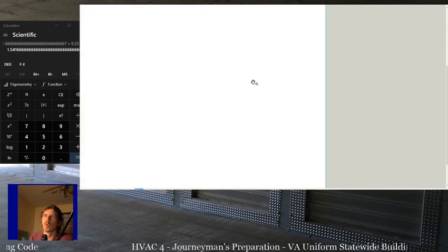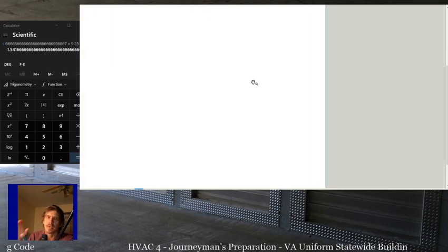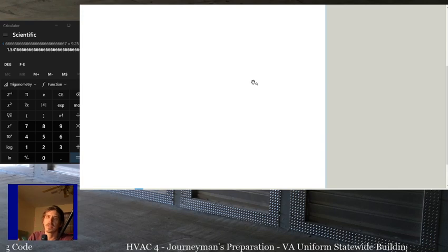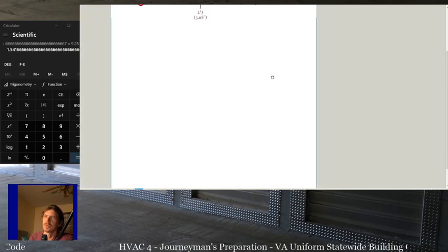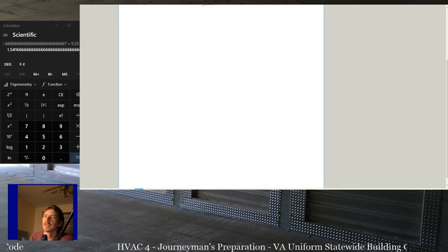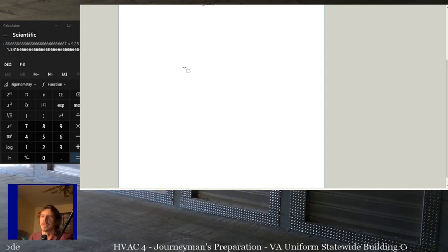Any short wall is usually a non-bearing wall. Generally, bearing walls will end up running almost the entire length of the structure. And if you get used to residential construction and even commercial construction for that matter, you can usually figure out what's bearing and what's not. But it's not something we can cover in this class in a reasonable amount of time.